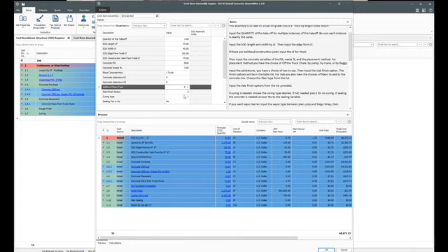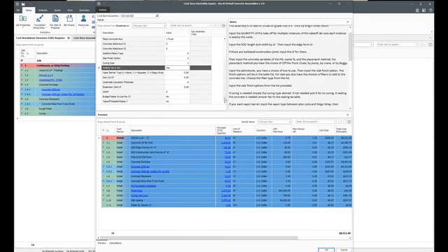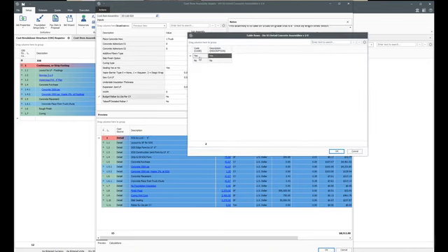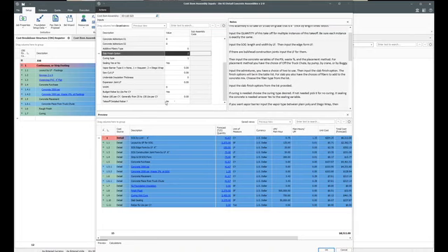Slab finish options, curing types. Now one is pre-fill for that. And sealing, yes or no. If I say yes, I will get sealant in there. And then there are questions for vapor barrier, saw cuts, under slab insulation, expansion joints, wire mesh, budget rebar, and detailed rebar. Budget rebar means, yes, I would like to take off the rebar, and I would like to input a pounds of rebar per cubic yard.